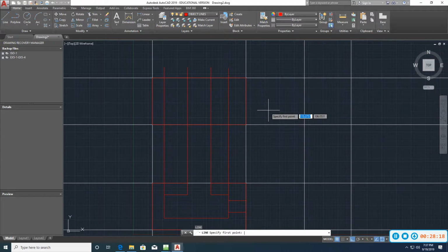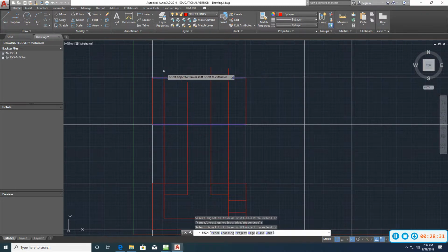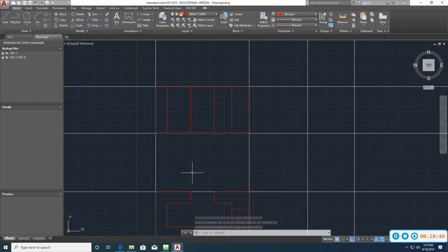All right, so I'm going to quiz you here a little bit. I'm going to trim up my lines first before I do. Just trimming. Enter. Now, when I point to a line, tell me if you can see that line if you were a bird flying over that block or looking down on that block. Tell me whether it's a hidden line or a solid line.